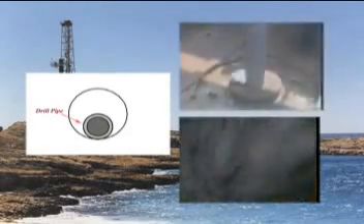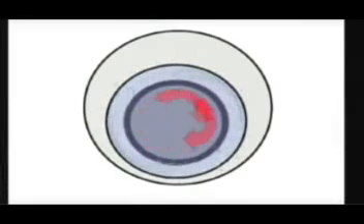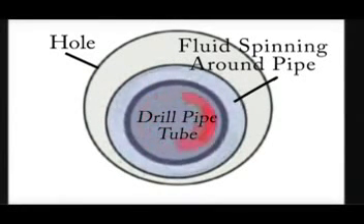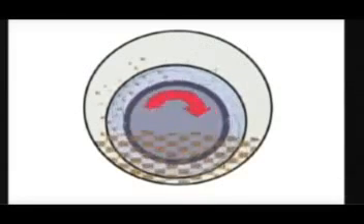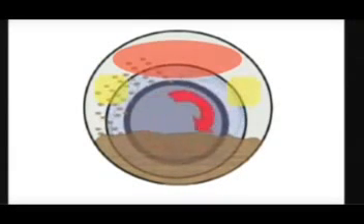Most of the hole cleaning takes place across the drill pipe tube. The high rotary speed and the viscous coupling between the drilling fluid and the drill pipe cause the fluid to spin around the pipe. This fluid movement picks the cuttings up and carries them into the flow regime on the top of the hole. Without this viscous coupling, hole cleaning in a laminar flow environment is reduced dramatically.